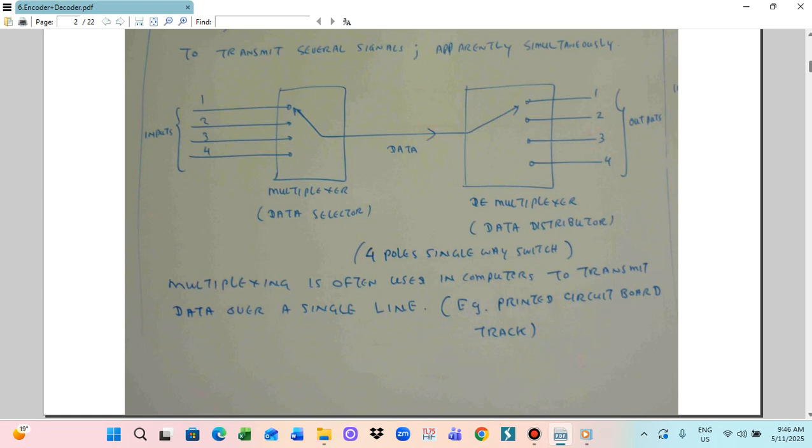The data control signal will be a character, a space, or a control command. Those can be represented by binary code. In this case, we utilize ASCII, the American Standard Code for Information Interchange. That standard code is utilized. This standard code has 7 binary digits, and it also has a hexadecimal equivalent. For example, the data A can be represented by the binary number 1000001 and the hexadecimal code 41. So this is the data transfer system we use.